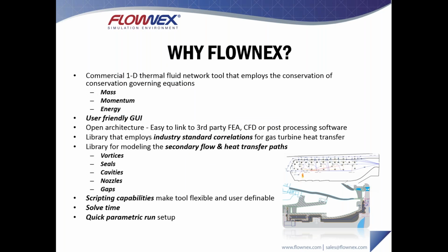Before I bring up a demo network, I just want to stress again why Flownex. For one, it's a 1D thermal fluid network tool that employs conservation of mass, momentum, and energy. It has a user-friendly interface. It has an open architecture which makes it easy to link to third-party FEA or CFD or post-processing software. It has a library that employs industry standard correlations for gas turbine heat transfer. It also has a complete library for modeling secondary flow and heat transfer paths.